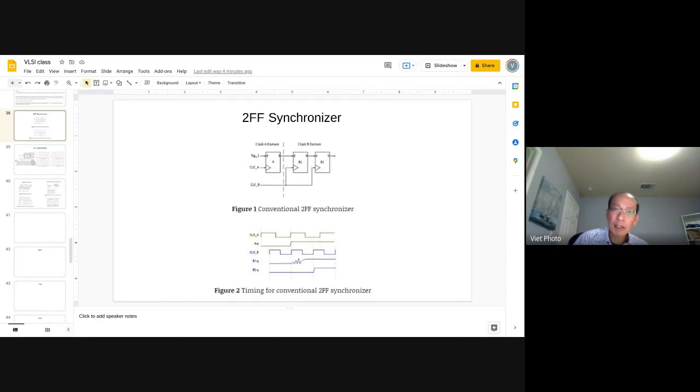So that's why we have this picture, because usually when metastability happens, it means that this one might go on forever. That's the theory. When we accept a certain amount of failure, like the yield, then most of the time it will happen like this. For one or two cases out of like a trillion, 1,000 trillion, it will not settle down.